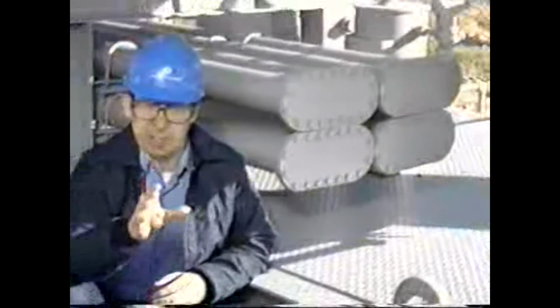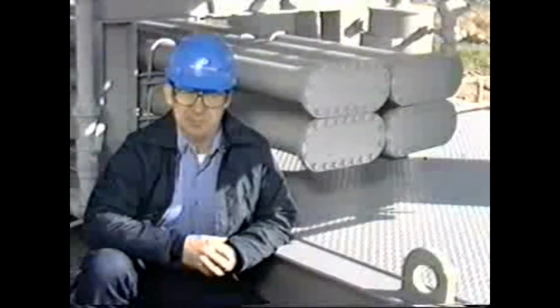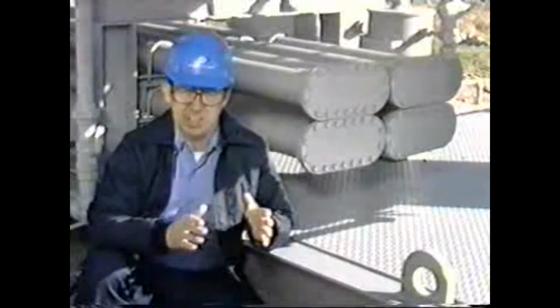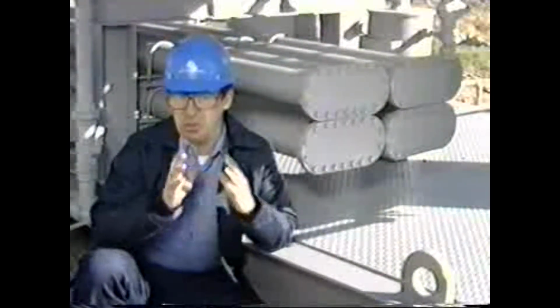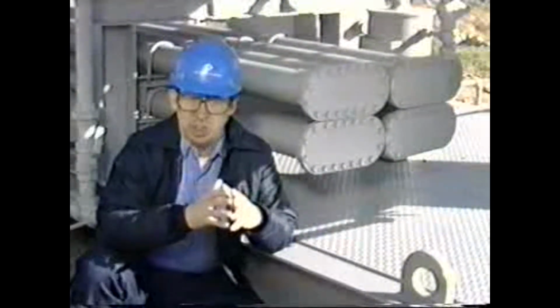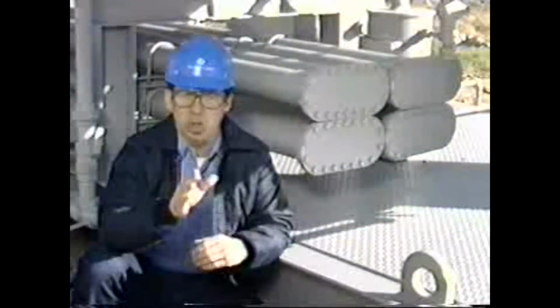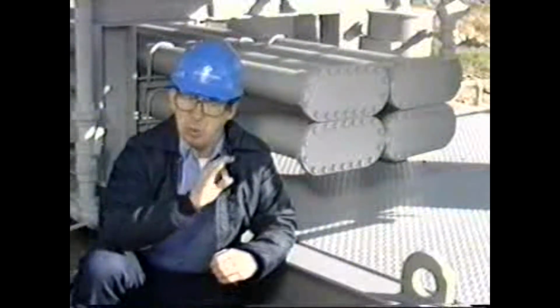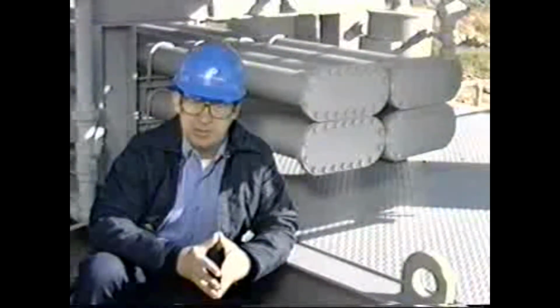There are two types of heat exchangers used to cool the glycol in a glycol dehydration unit. Glycol to glycol heat exchangers, like these, and a glycol to gas heat exchanger. Now, lean glycol leaving the surge tank must be cooled prior to entering the contactor. The cooling allows the lean glycol to absorb the maximum quantity of water from the gas in the contactor.